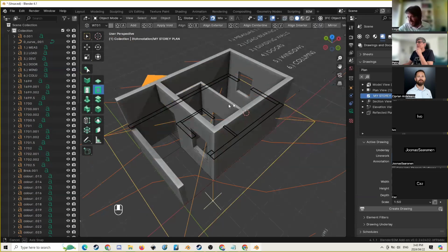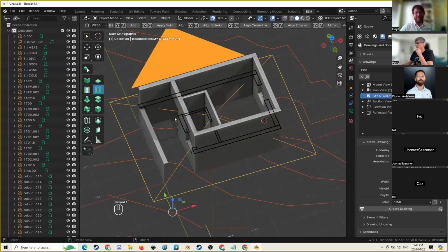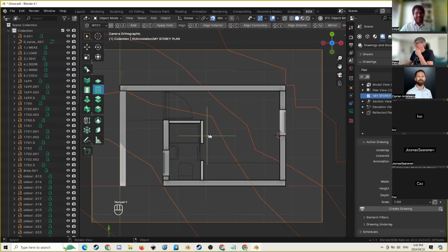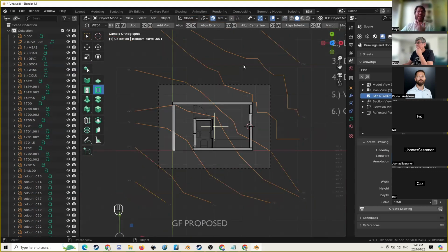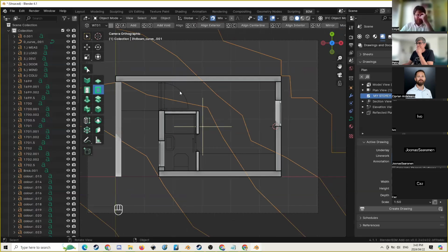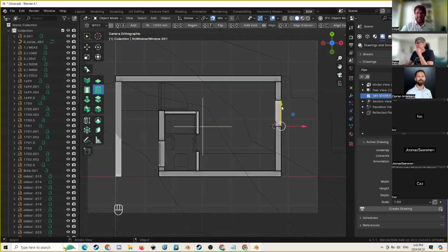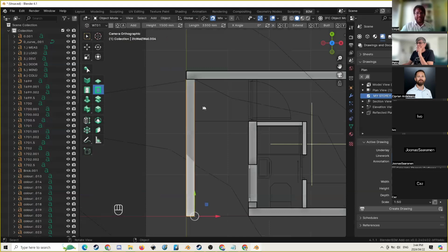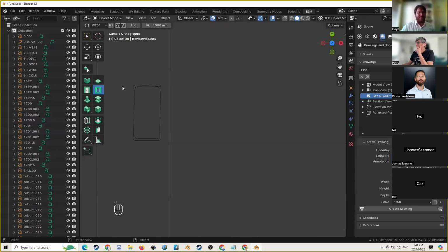And there is just one thing I want to show before we wrap up, which is converting this DXF into an IFC annotation, which is actually how you would store it inside of the IFC file, which does require 2D information. It does require a CAD view to store it in, and it is a little bit tedious, essentially. So basically, we've modeled in the windows and doors, and we've modeled in the walls all the way around. And there is also a rectangular hollow section here, which we had at 75 by 150.